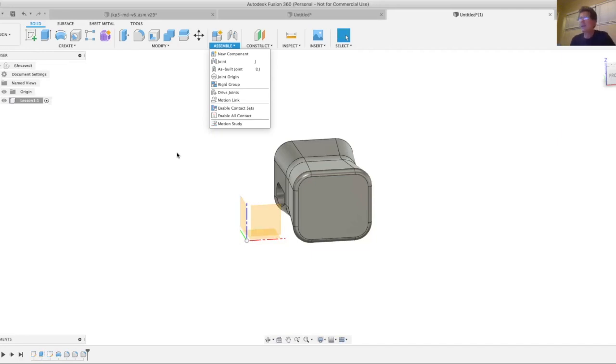And when you bring in, STL doesn't define a 3D object typically. This is an odd thing to say, I realize, since its main purpose is 3D printing. But an STL file uses triangles of various sizes and resolution to approximate the external skin of a 3D object. And when you import a surface model like STL, or in some cases STEP can be surface model, IGES is a surface model typically as well.